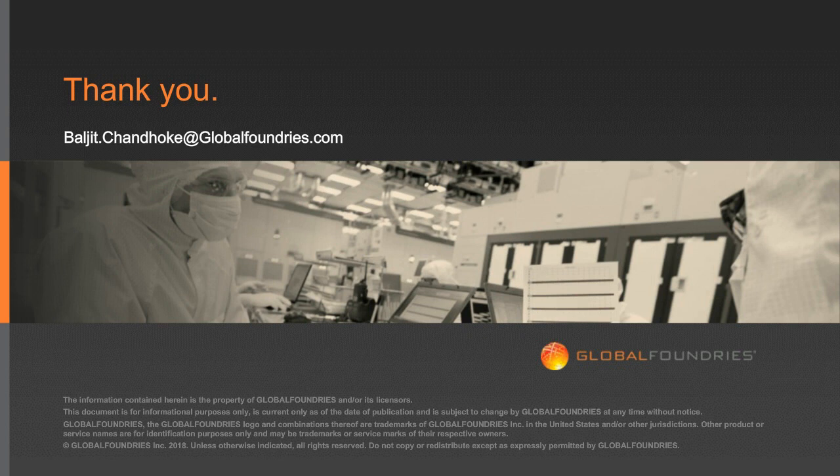SiGe can probably go to slightly higher output power, but 45 RF SOI has a superior switch versus the silicon germanium technology. And then the whole package of combining your power amplifier, your switch, and your low noise amplifier is exceptional. That's what you get: that integration. And we have an exceptional low noise amplifier in 45 RF SOI. Different technologies have different trade-offs, but what we have seen is the sweet spot of combining the switch, the LNA, and the PA with 45 RF SOI.